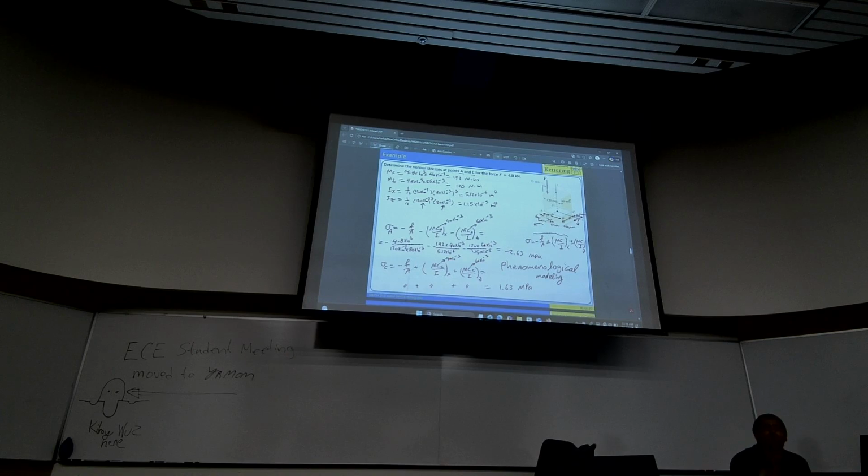What is that? So we talked about Hooke's law, right? Open question. What is Hooke's law? Raise your hand. Josiah? Sigma equals epsilon times E. Very good. Sigma equals E epsilon. And we said it's not a law because it's not always correct. It's only correct in the elastic region, right? We said in the elastic region, like this. In this very region, elastic region, sigma equals E epsilon.